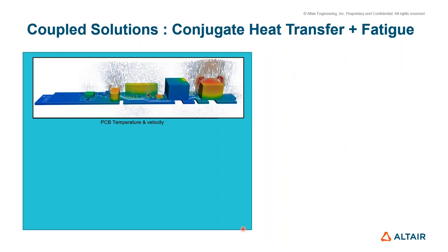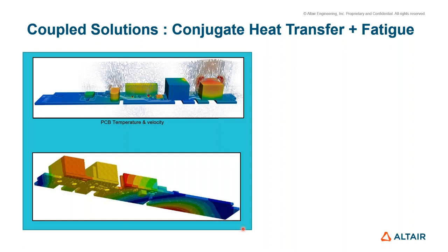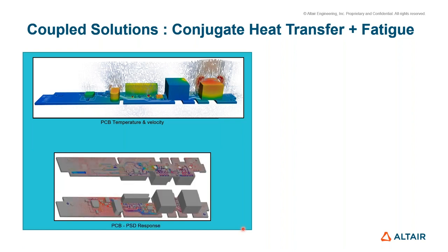Now, followed by this, the PCB goes through a certain set of mechanical strength tests. We would want to make sure that the pressures and temperatures which are dealt with in the CFD are taken care of as a preloading condition. And then an excitation load is applied to calculate PSD stresses or any kind of fatigue studies that have to be done on this PCB. It looks very small, has a complex system, and needs very good attention in terms of design KPIs from our side.